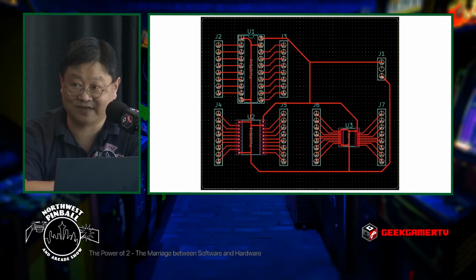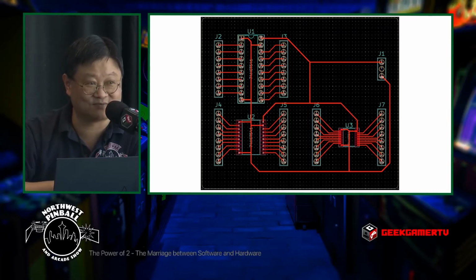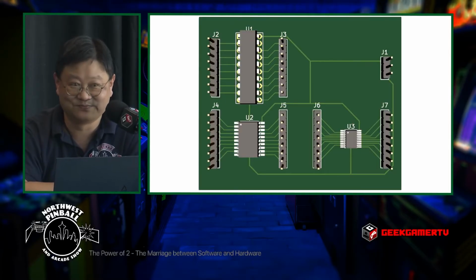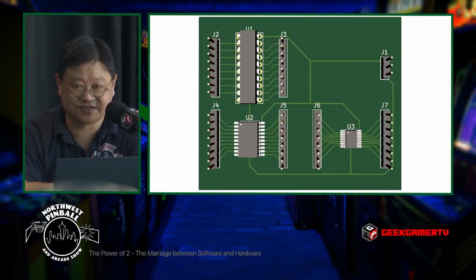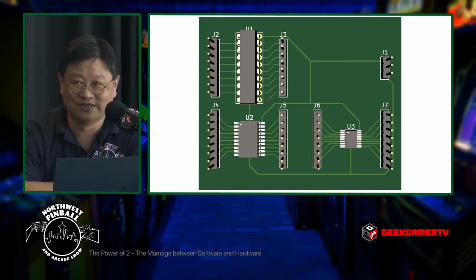And this is the point I'm trying to make: the schematic is logical, the board is physical. If you look at this and it doesn't make sense to you, well, that's what the board would look like. Three identical circuits, three completely different layouts. And this is just a very simple, contrived example. It can get much, much more complicated than this. Always use the schematic to look at the logical connections. Follow the copper traces, if need be, to find where they are physically connected.